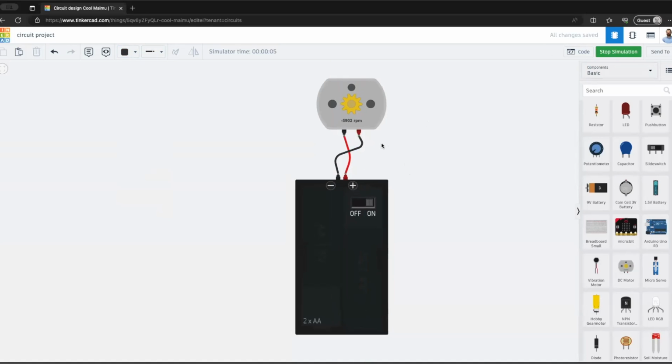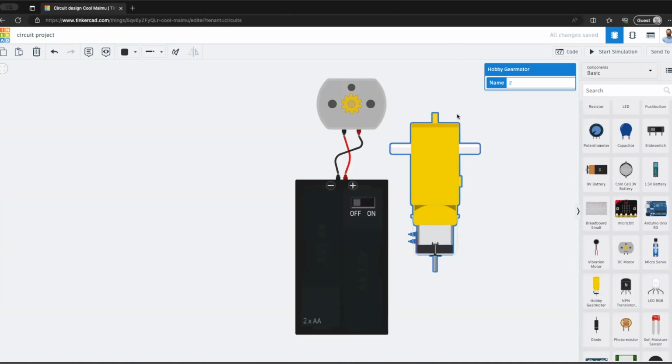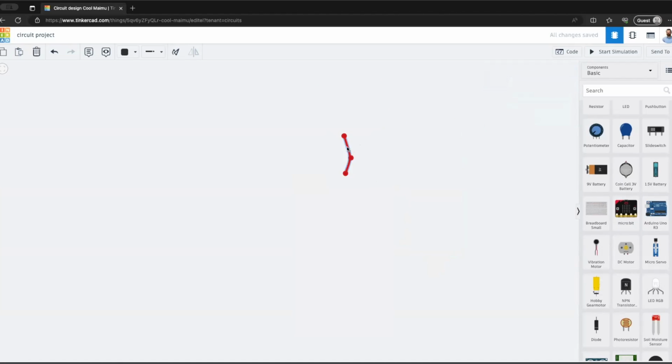And that's because while motors are often labeled, a DC motor like this is reversible in polarity. So if you hook it up one way, it'll spin clockwise. If you hook it up another way, it'll spin counterclockwise. That's kind of unique to DC motors, right? Servo motors and stepper motors, those are a little bit different. We'll talk about those later on. But these hobby motors and things like that work really cool in that way. So again, we're experimenting with electricity as we go ahead and as we build.